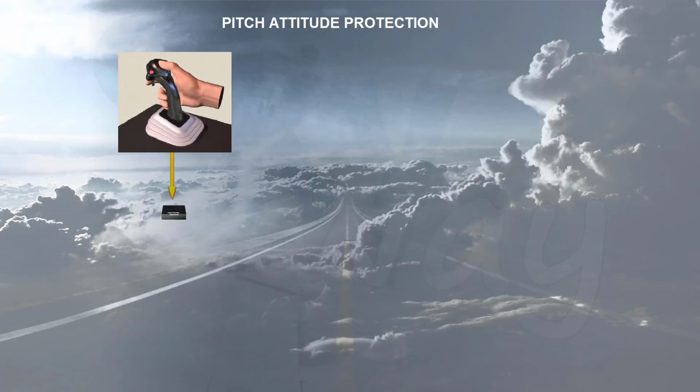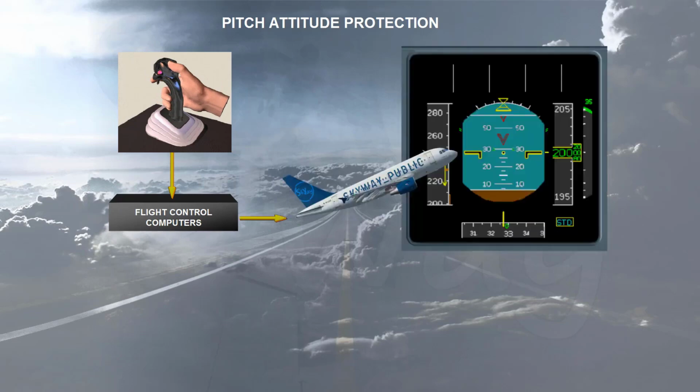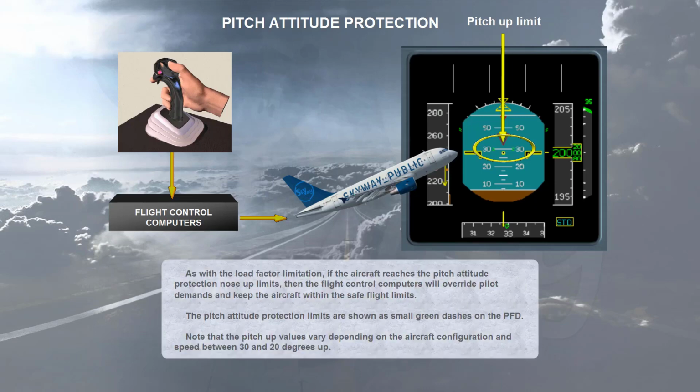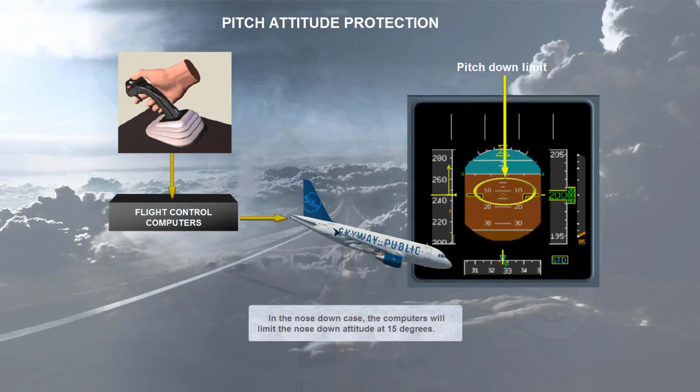As with the load factor limitation, if the aircraft reaches the pitch attitude protection nose up limits, then the flight control computers will override pilot demands and keep the aircraft within the safe flight limits. The pitch attitude protection limits are shown as small green dashes on the PFD. Note that the pitch up values vary depending on the aircraft configuration and speed, between 30 and 20 degrees up. In the nose down case, the computers will limit the nose down attitude at 15 degrees.